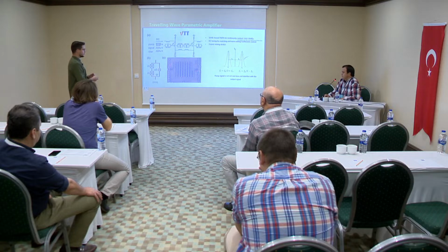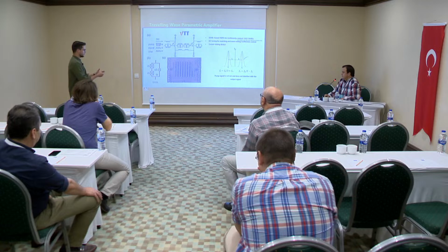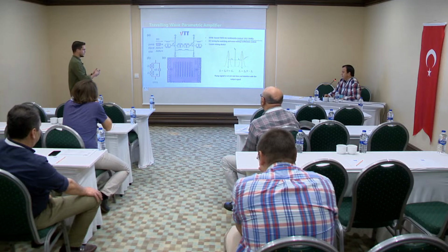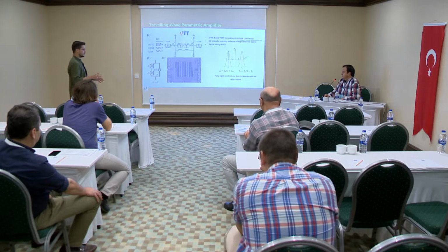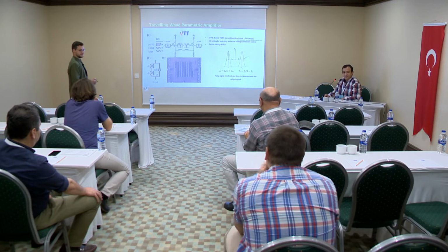It's a distributed system, and of course, these microwaves or these upconverted photons, we do not know exactly where they were born, right? So we needed to consider the distributed nature of gain and losses in our TWPA. We also performed some theoretical analysis on this. But basically, you can take into account the losses of your TWPA and take the worst case scenario to verify that the entanglement was indeed created. But where exactly it was generated, we unfortunately don't know. Yes, it's a good question.